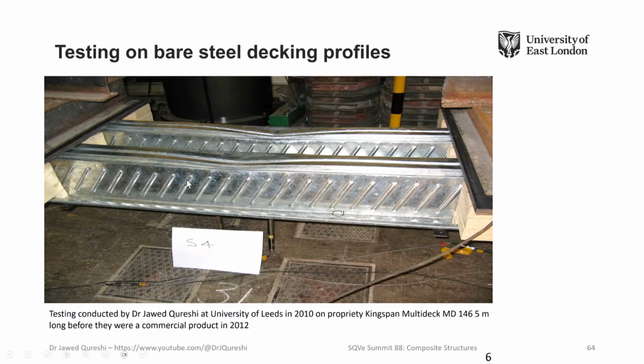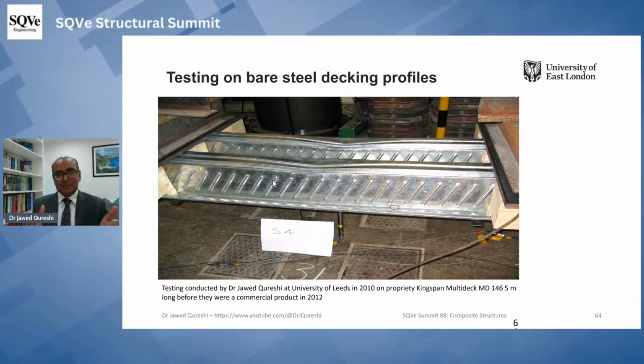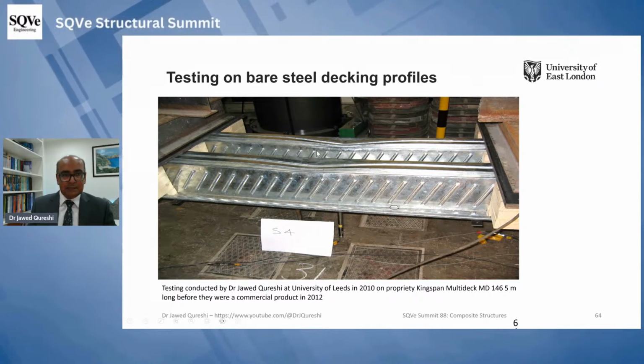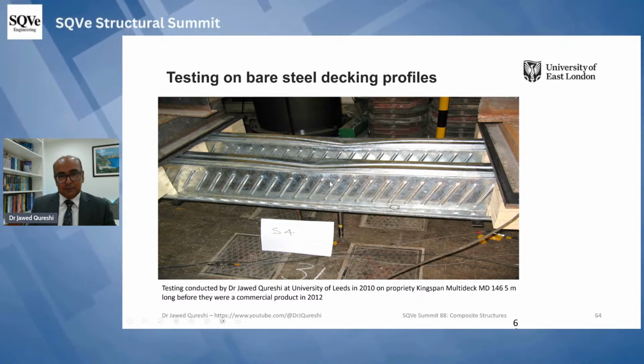Which in itself provides a resistance. It means that it is resisting it from moving in longitudinal direction. So it is providing longitudinal shear resistance to concrete, because the direction of these embossments is reversed on the other side of the deck. So it is left to right on the visible side. The web which is not visible, it is from right to left.